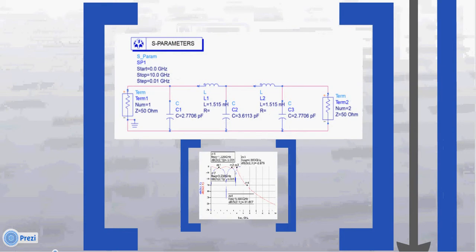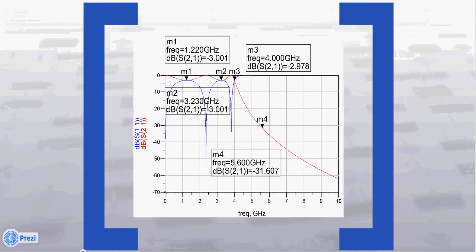Then the elements of the low-pass filter were found by looking at table 8.4 labeled with 3 dB equal ripple. The prototype element values were used to calculate the scaled values of the lumped elements in our low-pass filter. The figure that is shown is a schematic of our low-pass prototype filter. This figure shows what we just explained.